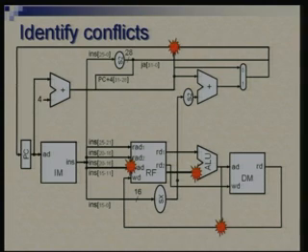This is also a point of conflict, where in instructions other than branch and jump, we simply want PC plus 4 to be sent back to PC, but in case of branch we have something else coming out of address calculation, and that needs to be going to the PC. And finally, this point where jump has one way of calculating address, branch has another way of calculating address, and ultimately they need to go to same destination.